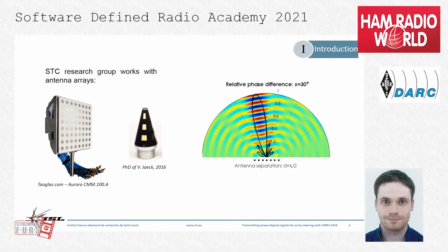Thanks to constructive and destructive interferences, the radiation pattern of the global antenna is more directive than that of the constitutive ones. Here, for example, you can see an antenna array made up of 7 elements that are represented by these black dots. And we show also interference figures. Constructive interference creates a lobe, while destructive interference almost completely cancels radiation in other directions in space.